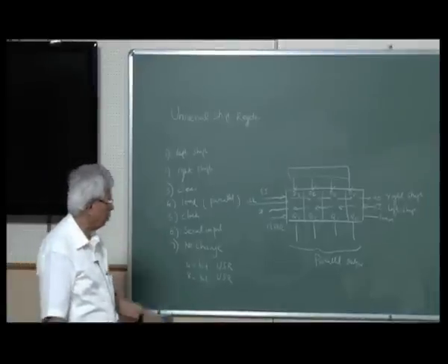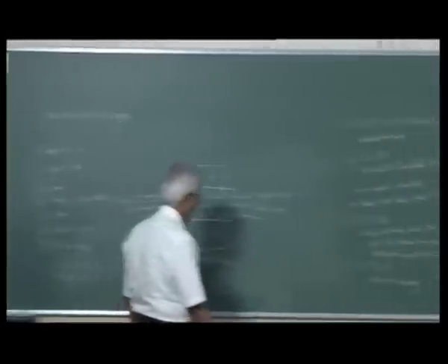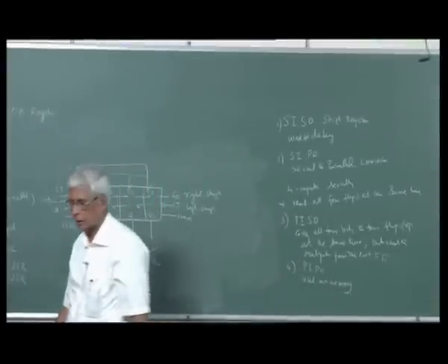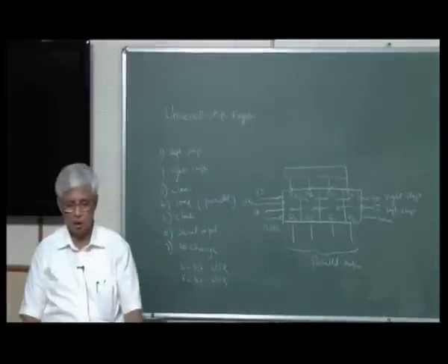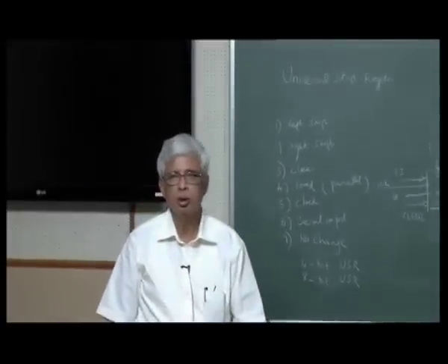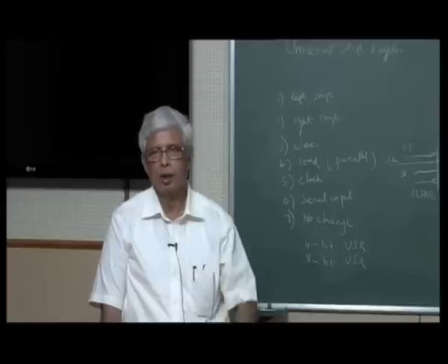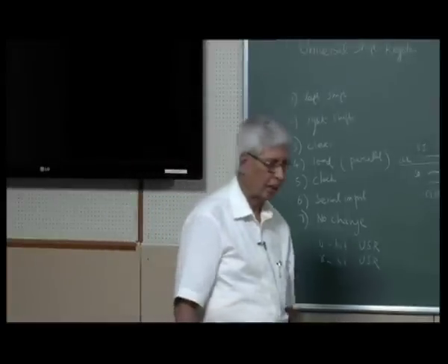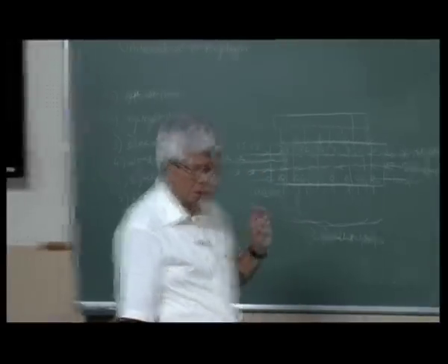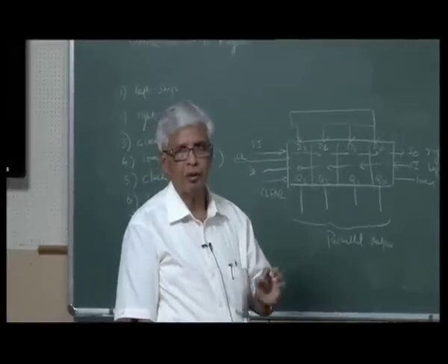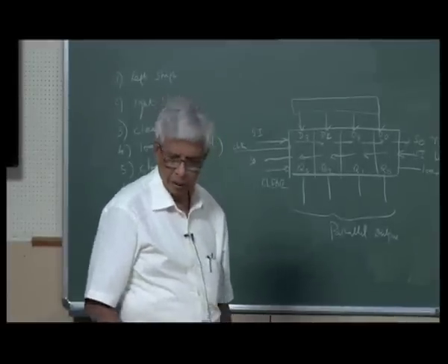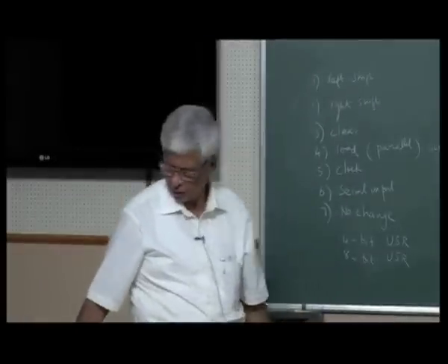So I said there are lots of uses for the shift registers, these 4 uses. Also they are used very much in other digital circuitry. We can use shift register to design counters. We can use shift register to design serial adders. Whenever you want something to be shifted, suppose you want to multiply 2 numbers using an adder, you can do this. Single adder, you put the numbers one at a time, 1 bit at a time, and shift it so that you can get the multiplication completed. There are other applications, but there is one application which is generally very useful